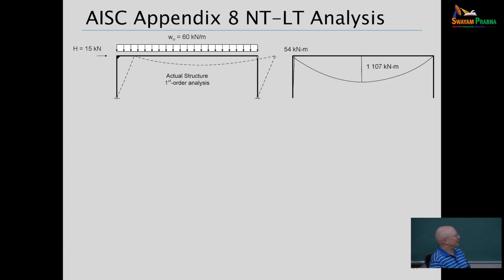Now I tell my students at Georgia Tech, if you go to Cambridge, Massachusetts to interview with LeMessurier and Associates, you may want to bone up on this frame and be ready. They might put it in front of you and ask you to explain what's going on. The one thing that is important to understand is, if we take away the lateral loading for a second, this frame would still have a significant side sway. Does that make sense? So why?